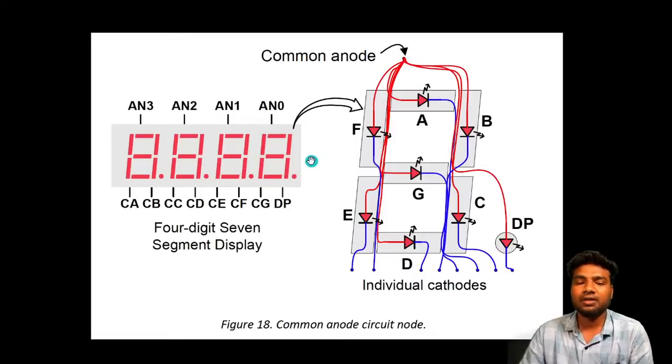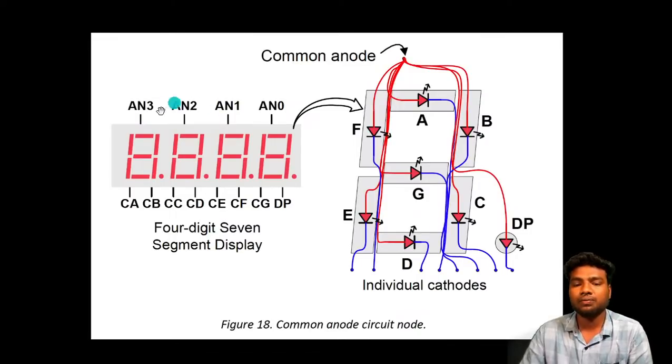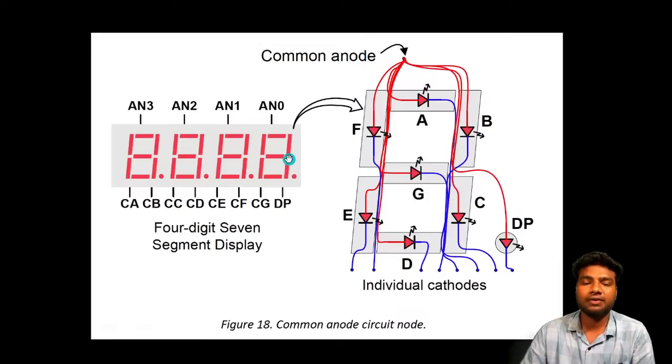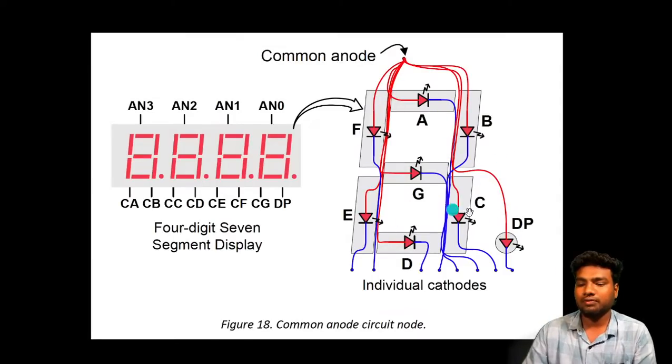To change from one segment to another very fast using the clock, we have to use the counter. Based on the counter only it will move. We can also give a clock divider. Clock divider and clock counter are not different things. Basically the purpose of both is the same: to increase the delay from the input clock oscillator.